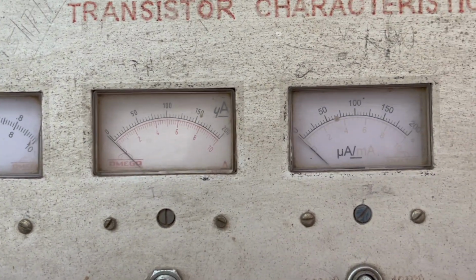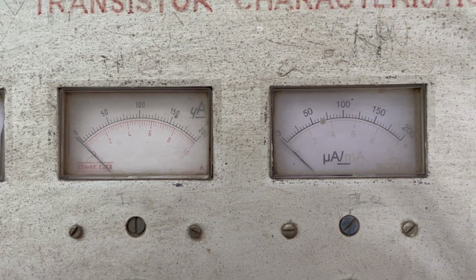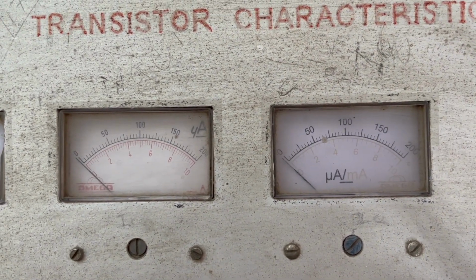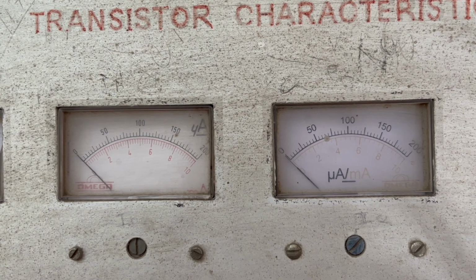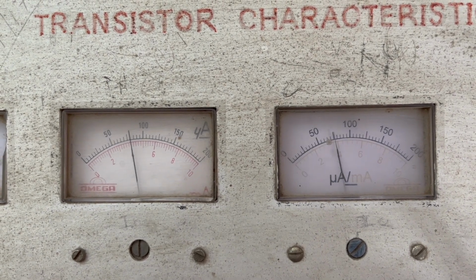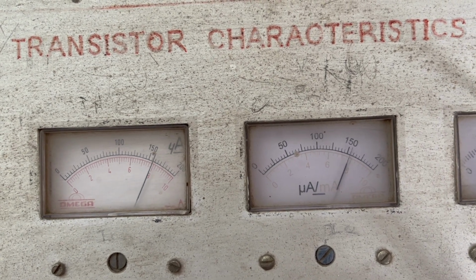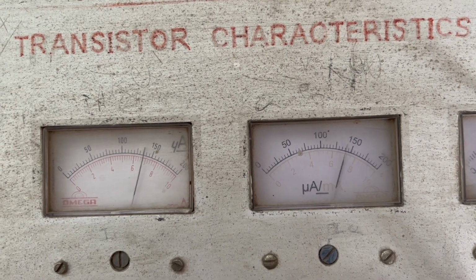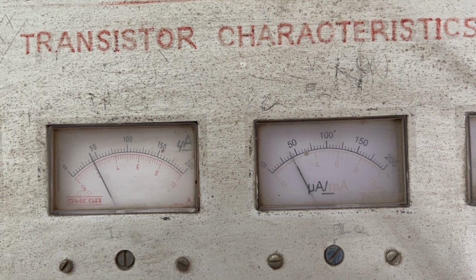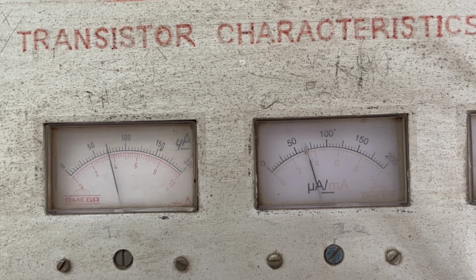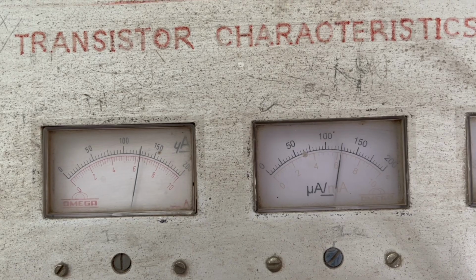And you can see here, when we increase the input supply, the emitter current and collector current are varying in exactly the same manner. They are replicas of each other because IC is alpha times IE, alpha is almost 1. So whatever is the emitter current, the same is the collector current, that you can observe here.